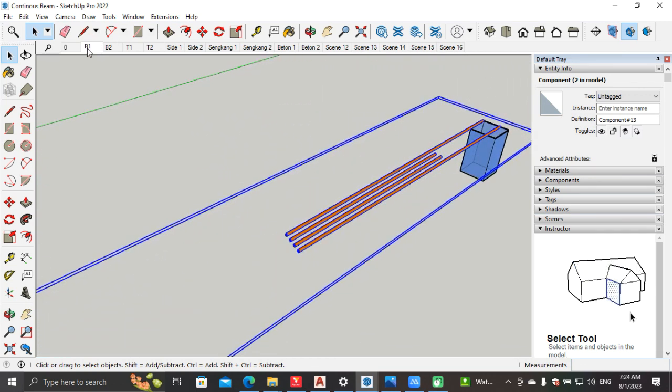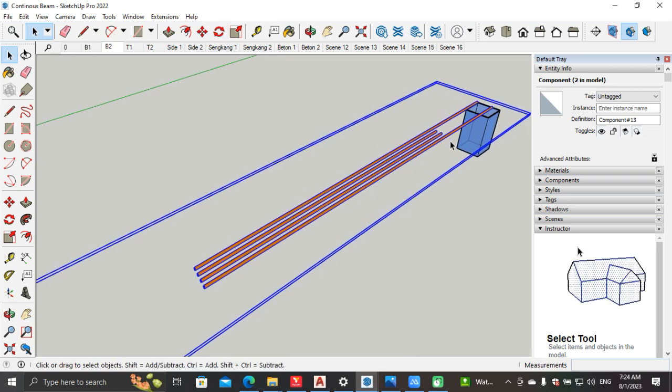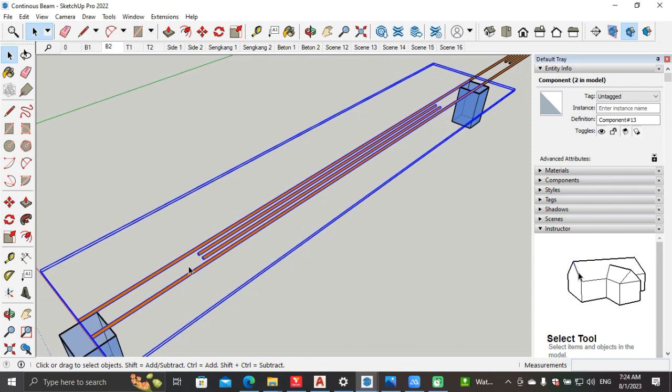So here, if you are seeing the bottom reinforcement, here you have given just 2 bars, that is the minimum number required to keep the cage structure. And towards the midspan, we need 4 number of bars. So we have given it as 4 numbers. That is, this is curtailed at this point.